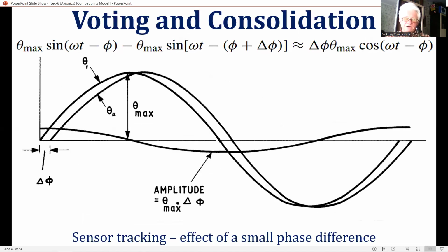As already mentioned, failures are detected by cross comparison and majority voting. However, it is necessary to allow for normal variations in the outputs of the parallel sensors measuring a particular quantity due to inherent errors in the sensors and their manufacturing tolerances. Normal errors in sensors include such parameters as scale factor errors, linearity errors, null or zero offset errors, hysteresis errors, and variation of the above parameters with temperature and ageing.